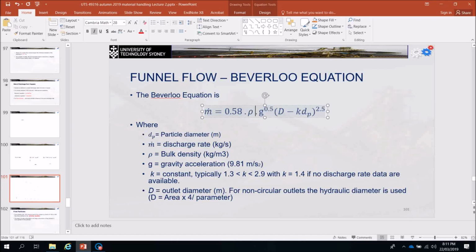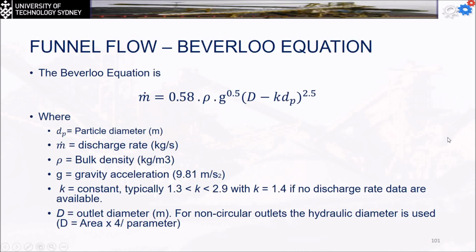Okay, now the particle diameter, let's take it as 500 instead of the 100 we have in the question. So both are going to be for the coarse material. Okay, so now we have two equations. Just remember the k here is going to be 1.4. And the d particle for both is in meters. So when we said 500 micrometers, you should change it to meters. That means you have to multiply it by 10 to the power minus 6. So 0.5 times 10 to the minus 3.